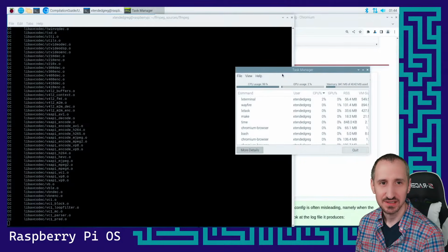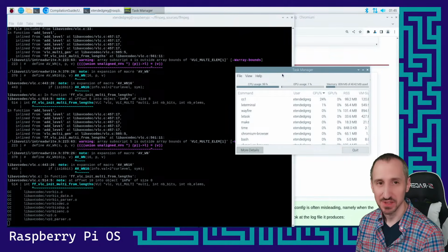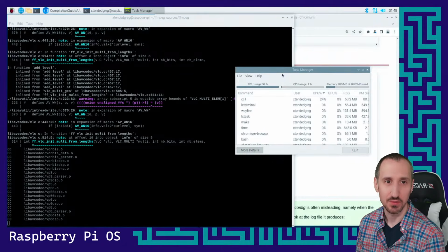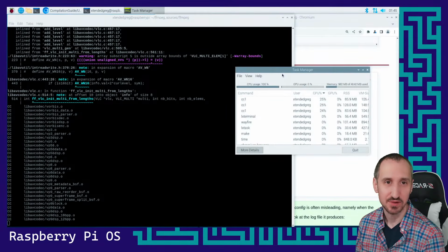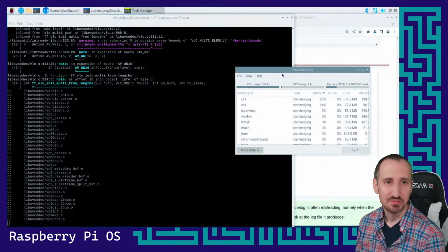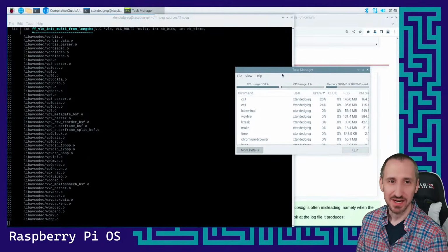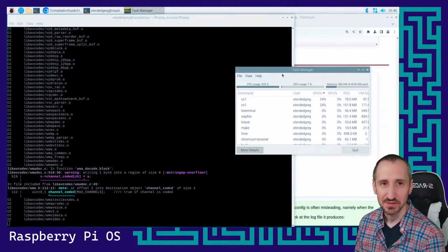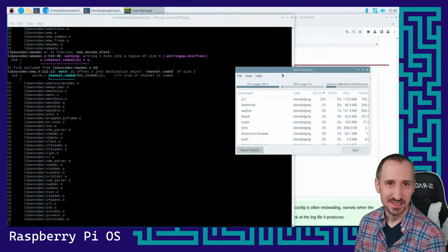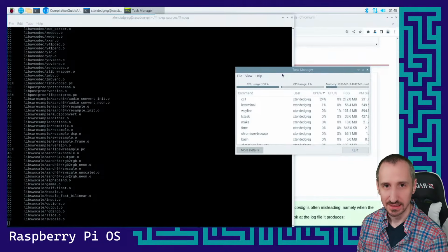One of the things I did is I took a Raspberry Pi Pico and hooked up some GPIO pins to what was a remote control for the KVM. The KVM wasn't very expensive from Amazon, just kind of arbitrary, but it had a separate HDMI and a separate USB, which was perfect for the Raspberry Pi since it's got the micro USB. Some have micro HDMI on the Raspberry Pi 5 and the Raspberry Pi 4, full-size HDMI on Raspberry Pi 3, 2, and 1, and then Pi 0 has the mini HDMI. So I wanted it to be interoperable with everything.